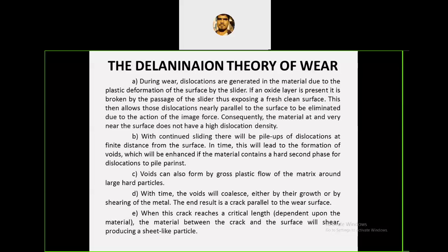What are you going to do? You take the specimen, one ISO standard specimen, and on that you apply the tensile load. Tensile load means it starts with 0, 100, 200, 300, 400, continuously increasing the load. And what happens? Is there any sudden fracture? If you apply a 0 load or a 100 load, will it fracture the specimen? No. Once the load crosses the ultimate strength of the material, it will cause the fracture. So before fracture, it will provide some indications.